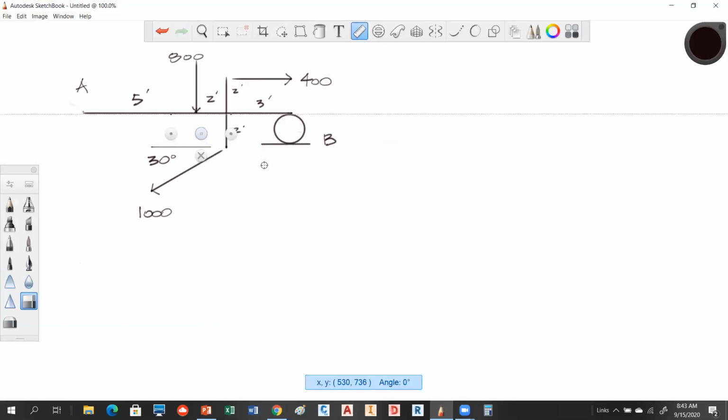I'm going to indicate them, and you tell me which way you think. So there's one here, and there's potentially one going this way. This one can go up or down. What do we want to do, up or down with it? Remember, it really doesn't matter. Up to the right. Okay, up and to the right. So we're going to call this the up and to the right reaction, and we're going to designate these R_AV and R_AH.